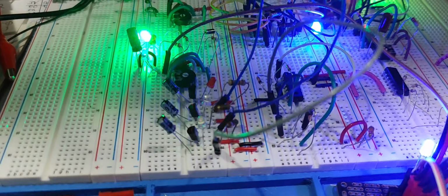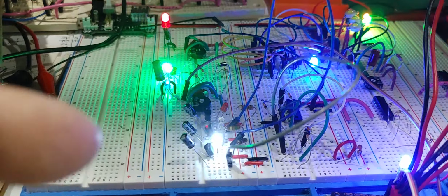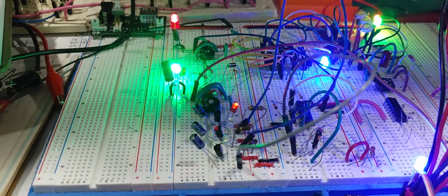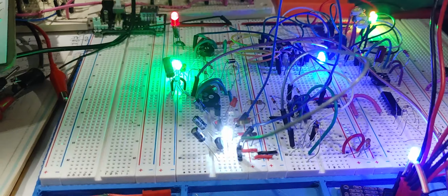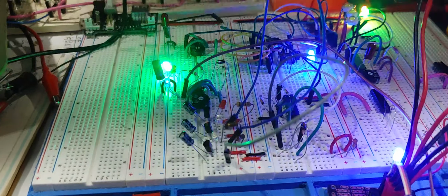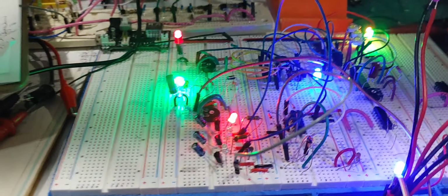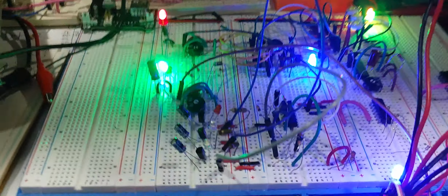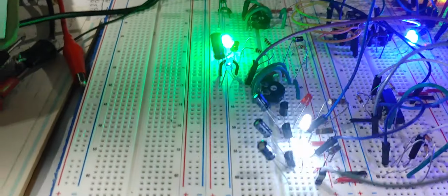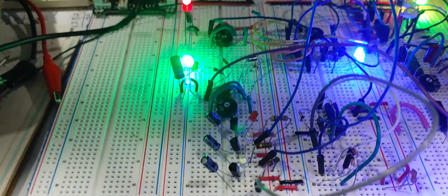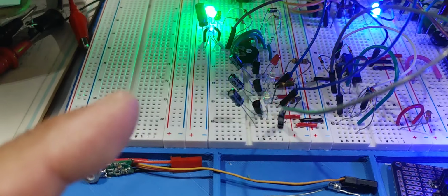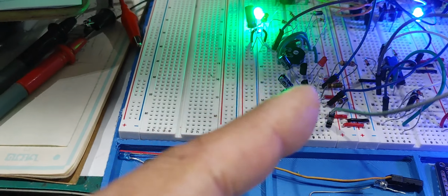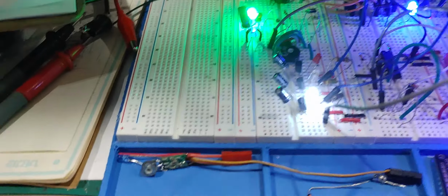By the way, I am using a single LiPo with these circuits, so these run at 4.2 volts maximum or 4 volts DC average. That is typical of a 1S LiPo battery. You can see how bright these things are at that 1S voltage, which is great for the little airplanes that I build these things for. You can go higher with the voltage, definitely, but in order to do that, I would have to change the current limiting resistors associated with each of these LEDs, and I'll show you that in the circuit in just a minute.